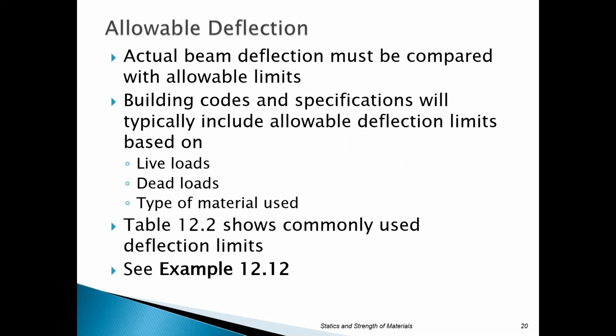So you can see for live loads, you have values. If it's a roof member or a floor member, you have snow load values, and you have dead plus live loads. A general equation that's nice to remember is that the allowable deflection would be 1/360th of the span. But again, that's not always true. You can see that it depends whether it's, for instance, a plastered ceiling or non-plastered, or those kinds of things.